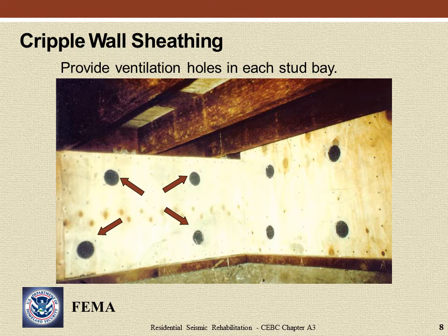Ventilation holes should be provided in each stud bay. Because it is possible for moisture to enter the stud bays, the holes provide for air circulation that can allow moisture to dissipate rather than accumulate and cause decay.